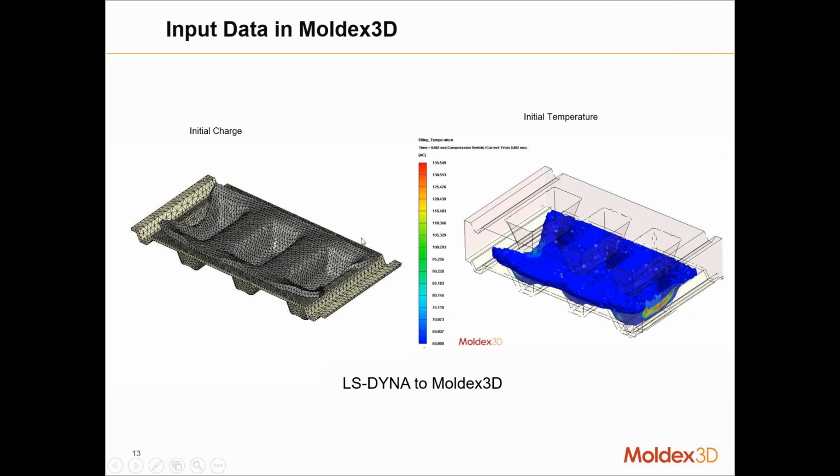We can see in gray the charge when it's being compressed still in the solid phase, kind of like the draping. And then we have our final part in the yellow. On the right, we can see the temperatures during that compression. That will be our initial boundary condition of the charge prior to Moldex 3D calculating the flow.